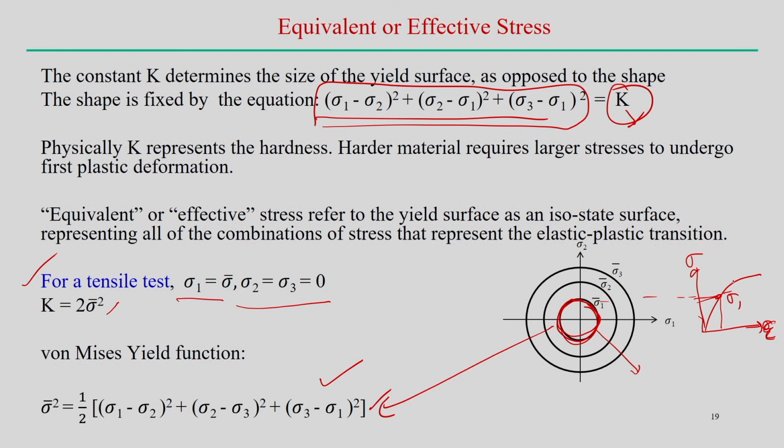Now, for example, after straining, the material becomes strain hardened, and the yielding point shifts to sigma 2 bar in this case. Similarly, after further strain hardening it can reach sigma 3 bar. In this case all represent isostress surfaces that correspond to the same functional form of sigma 1, sigma 2, sigma 3, but the k value is actually changing, and that takes care of the strain hardening effect, and evolves the yield surface by accounting for the effect of strain hardening during the deformation process.